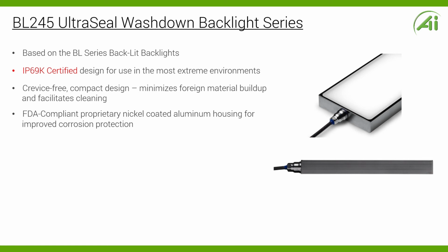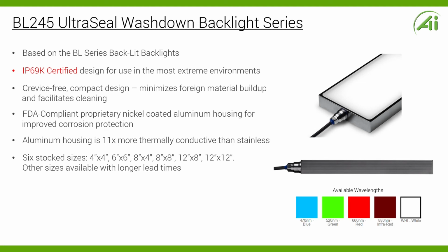They are FDA compliant in the sense that we use a proprietary nickel phosphorus coating that's very even, and it improves corrosion protection considerably. In fact, it's less corrosive than stainless steel. The housings are also much more thermally conductive than stainless, which is a big advantage in a hot environment where you're always concerned with keeping heat away from the LEDs, because that is essentially how they are destroyed. We have multiple sizes that we stock as well.